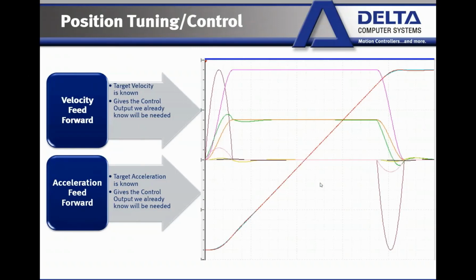Okay. The feed forwards work a little bit differently. Rather than like the PID, where there's a range of answers that could work with your system, the feed forwards generally have one correct setting if you have a linear system. And again, that kind of goes back to our recommendation for the valve. We recommend having that zero overlap or slightly underlap linear valve.